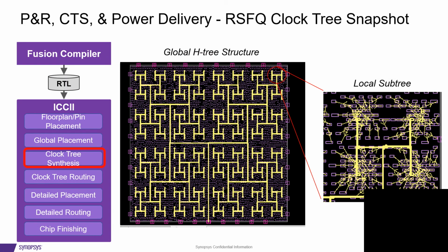Now, let's go to the 2901 place and route that I mentioned at the very beginning of the talk, which is what we use to establish a methodology for our back end, starting with synthesis all the way through chip finishing. Again, I want to stress that we decided to go with a methodology of using PTL, passive transmission lines, for our interconnect.